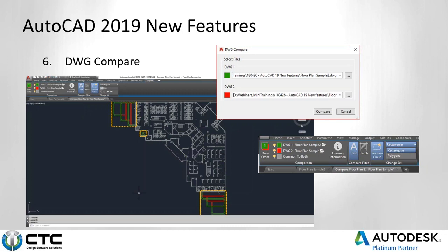And then you have control to be able to change the color after you create the comparison or before you create the comparison. You can change the colors. Then also you can turn off the revision clouds if you don't want to see them. Or you can change the shape of the revision cloud from rectangular to polygonal, and then you can adjust how big that revision cloud is, the size of it, and how precise it is going to get. So if it's a big change, it might be a bigger box, but if you shrink the margin of it, it might grow bigger and make a massive area or a smaller area closer to the change. And I'll actually show this off here.